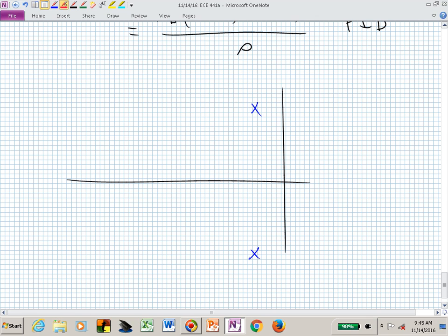What if somebody says, well, the pole was there, now I want to put two zeros there. What's the root locus going to look like for this pattern of poles and zeros in a PID controller? I have quite a bit of flexibility in selecting those zeros.